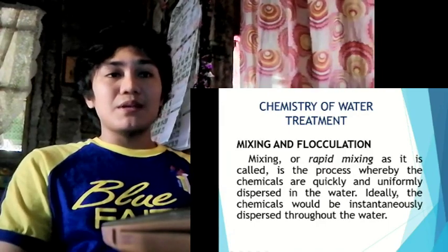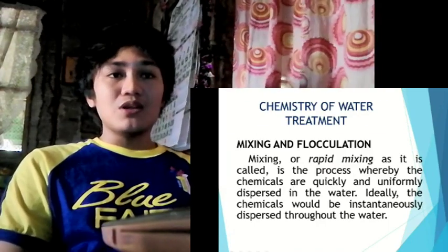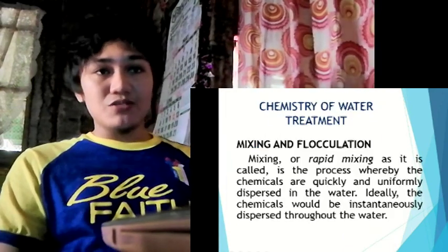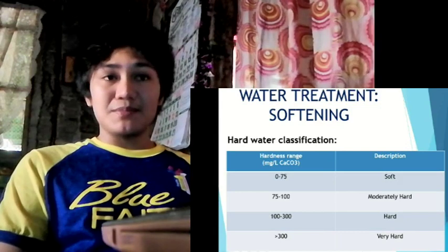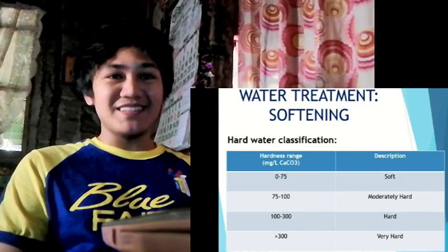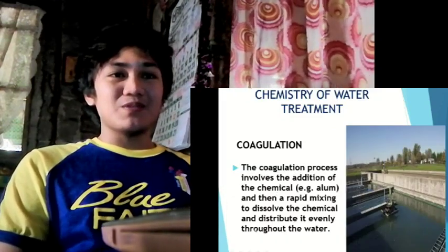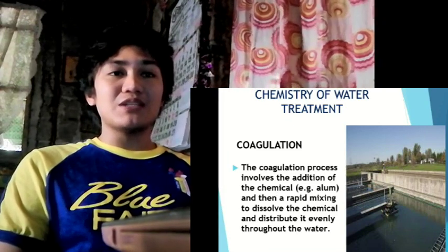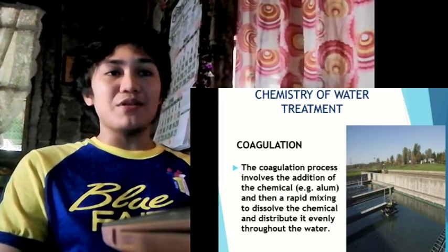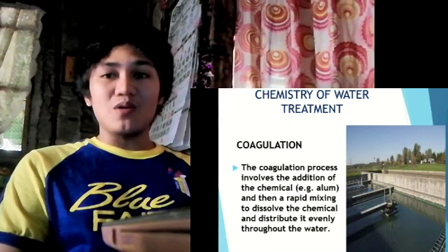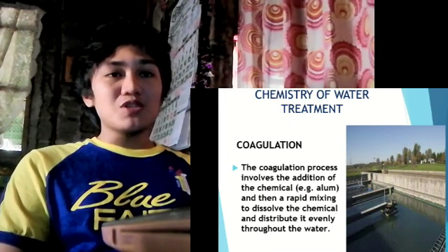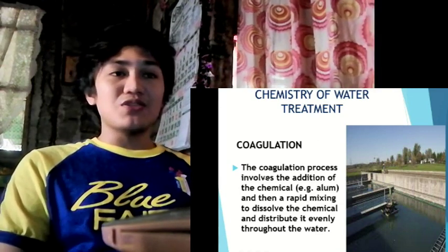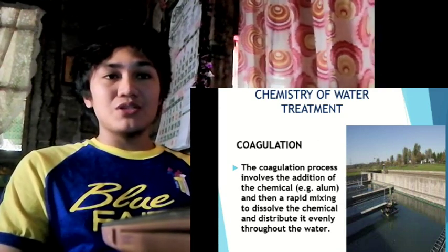Colloid destabilization. Colloids are stable because of their surface charge. In order to destabilize the particles, we must neutralize this charge. Such neutralization can take place by addition of ion of opposite charge to the colloid. Since most colloids found in water are negatively charged, the addition of sodium ions should reduce the charge.